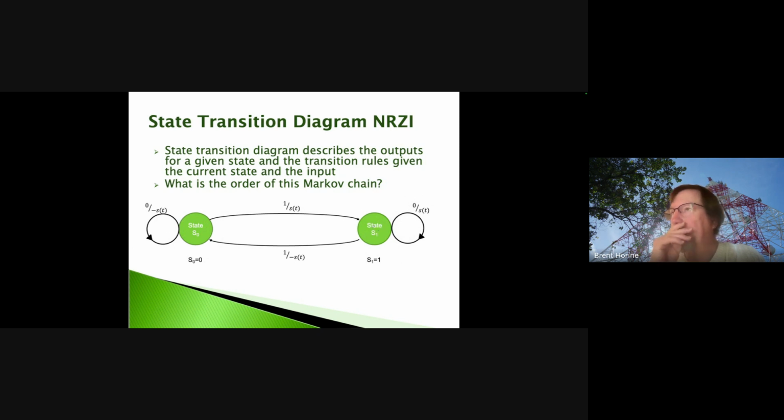And then here, if we get a 1 value in and we're already at 1, we'll transition to state 0. And if we're in state 0 and we get a 1, well, that exclusive OR puts us over here to state 1.